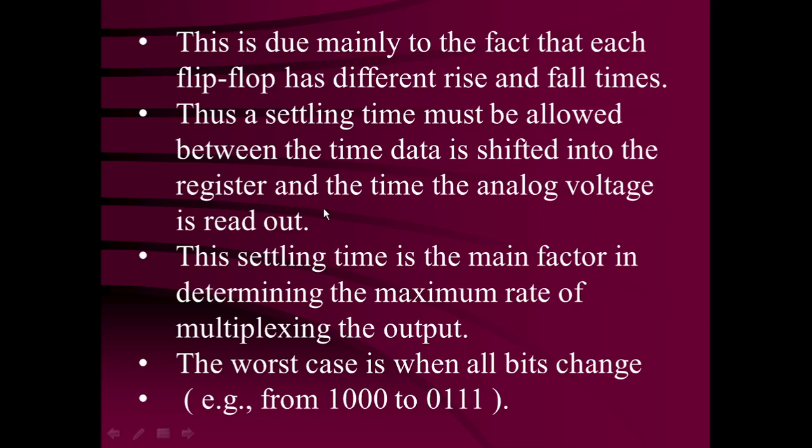So whatever the digital information is coming out of the flip-flop, each bit will have a different propagation delay time, and hence you have to wait for the settling time, and accordingly the sampling of the input signal should be provided.